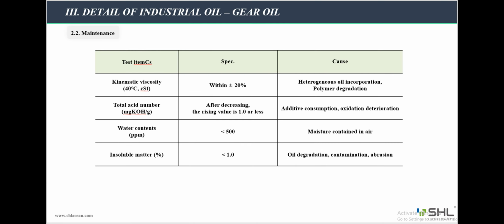Regarding oil management, like hydraulic oil, gear oil also needs to be managed in terms of viscosity with a change of no more than 20% compared to new oil, acid content less than 1 mg KOH/g, water content less than 500 ppm, and insoluble matter less than 1%.